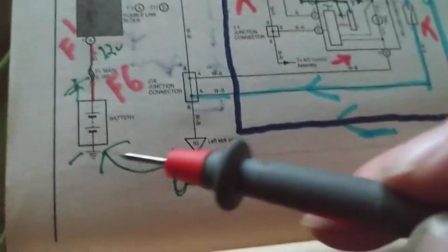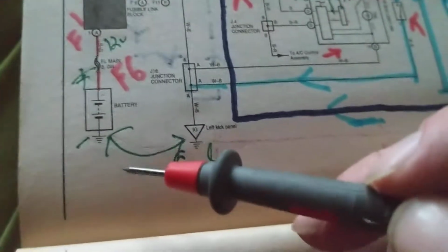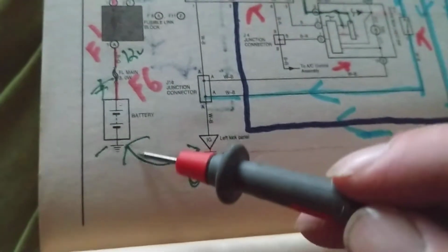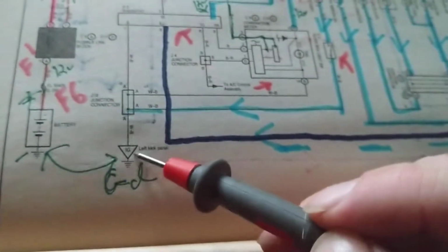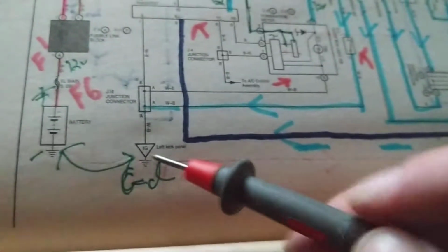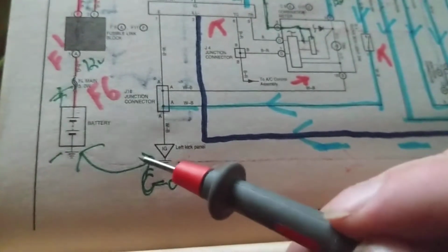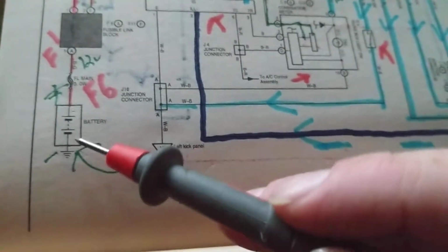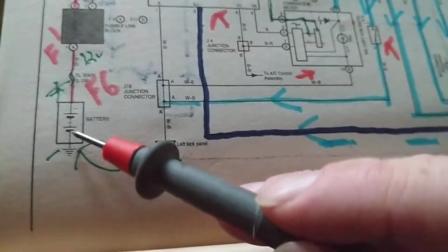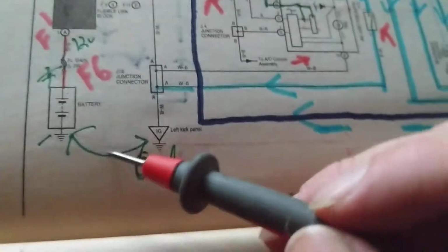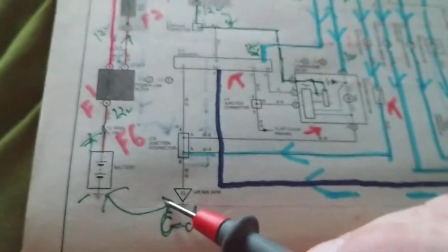Now usually when we measure current with a meter in series, we put it to the negative. Where is the negative? Right here, the ground. So we take the negative of the meter here, and the positive goes to the other place, wherever it would be connected to the other cable. Take the cable off, the negative, right? The negative goes here, and a positive cable goes here. We go back to the negative terminal, and the positive goes to the cable. That will give us the total current.